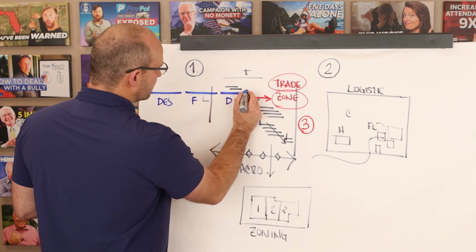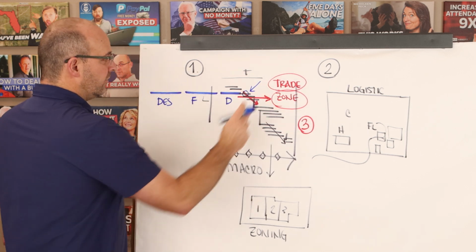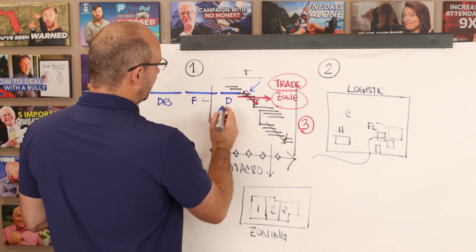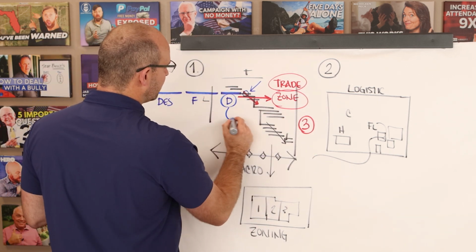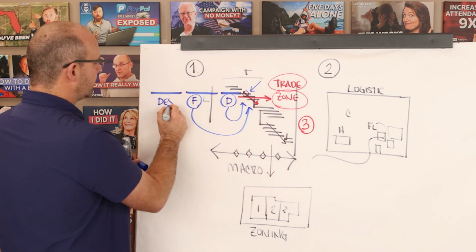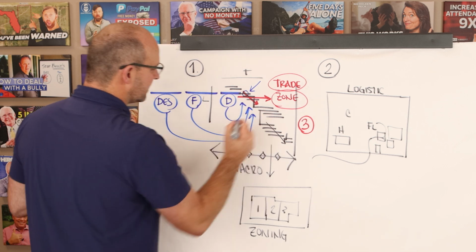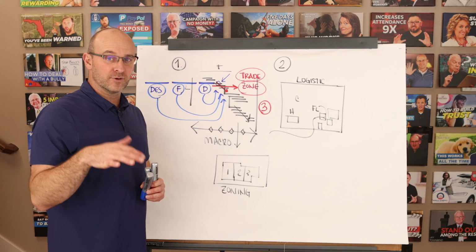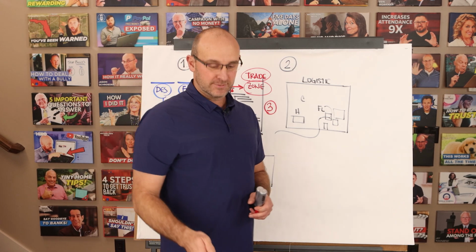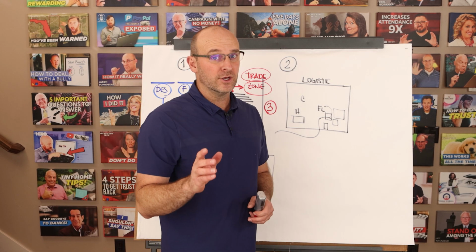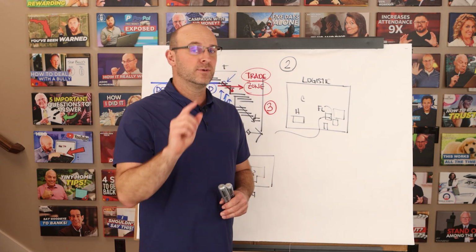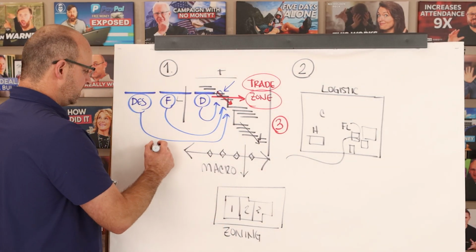So the question is, what duration do I need here for my trade bottleneck or for key bottlenecks inside the system? And the question is, how can I deliver it differently to enable the crew? How can I fabricate it differently to enable the crew? How can I design it differently with possibly a different configuration or material type or equipment type to enable the work of that crew? And that's absolutely crucial. So in your planning, you're really going to want to look at this. And so I'm mentioning things that are typically not done, but that should be done. And so that is number 4.